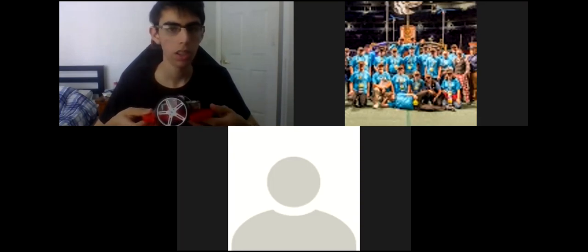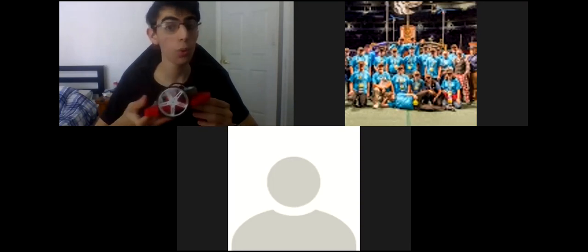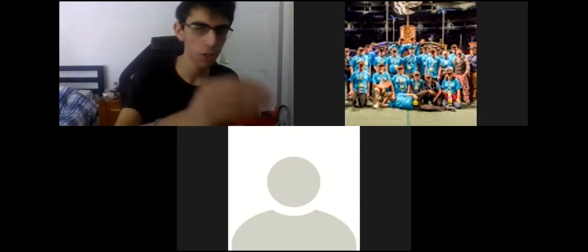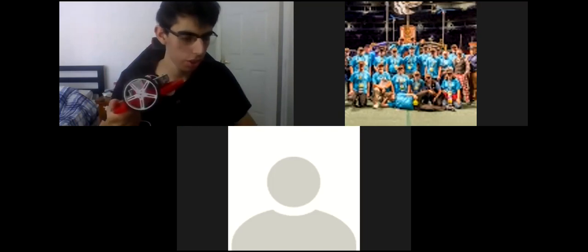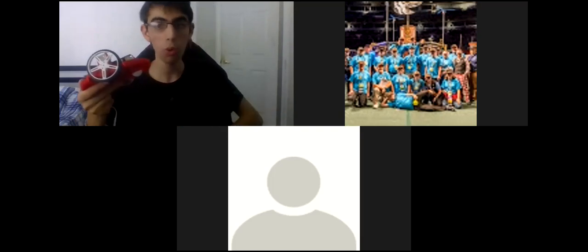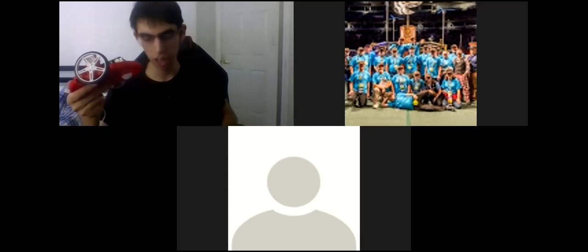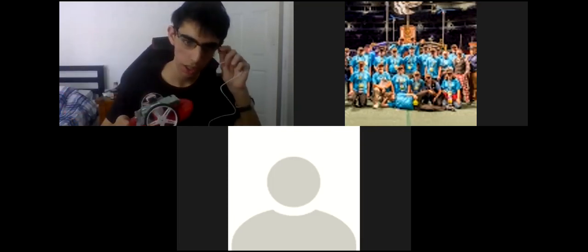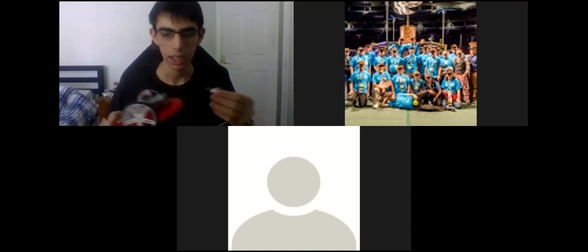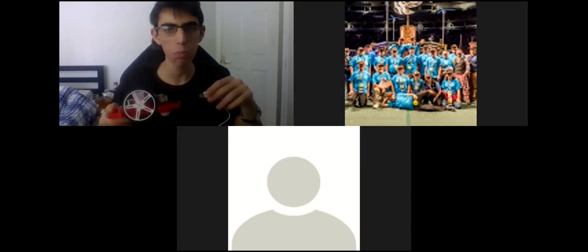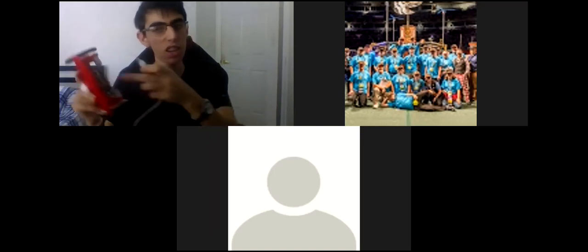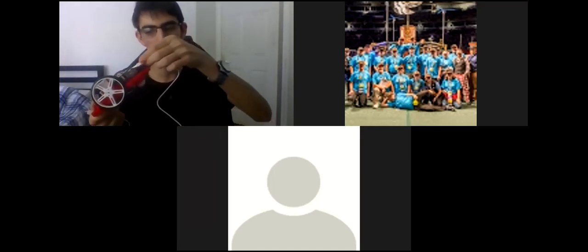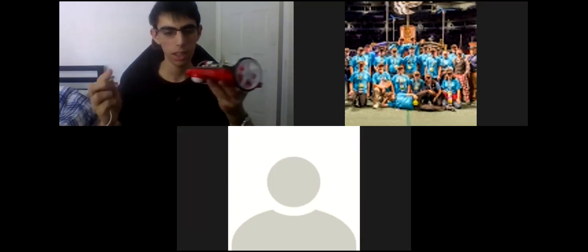Yeah, for sure. Wonderful. So after that, we're gonna use the micro USB cable to connect the Romi to the blackboard, which is the low level connection because it doesn't take much. It just gets the input and that's what it's being told to do, like a thought. And then the Raspberry Pi, which is the mastermind, you're gonna connect the USB to the Raspberry Pi. Also, all of this needs to be turned off.